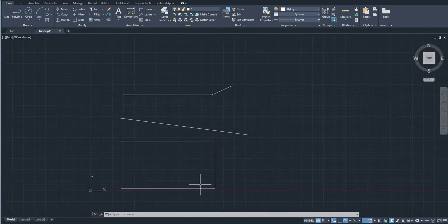As I just made these lines by entering some units, you didn't know what these units were: millimeters, feet, inches, whatever. I'm going to tell you how to edit units. Now before that, let me just make it very, very clear that whenever you make an AutoCAD drawing, just try to make it at a scale of 1:1. You only have to scale it while plotting it. You can scale the drawing while you plot it.